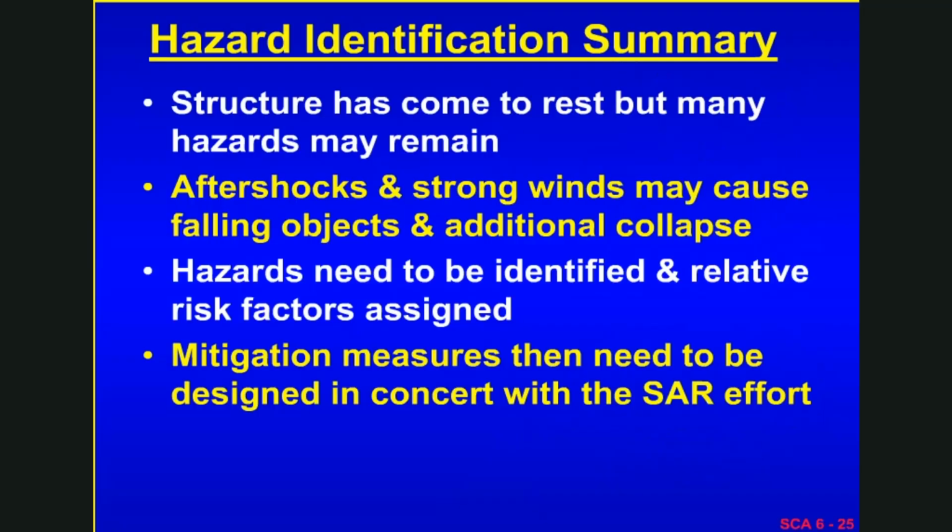So in summary, structures come to rest. That doesn't mean that they're stable. It means that they're at rest. They've experienced lots of movement, perhaps. They've sort of been collapsed into a shape, and so that's absorbed a lot of energy. That's a good thing. On the other hand, if we have aftershocks or strong winds, that can change that at-rest condition. Also, when we remove things or change things, we may change the situation and cause the structure to move a little bit more.